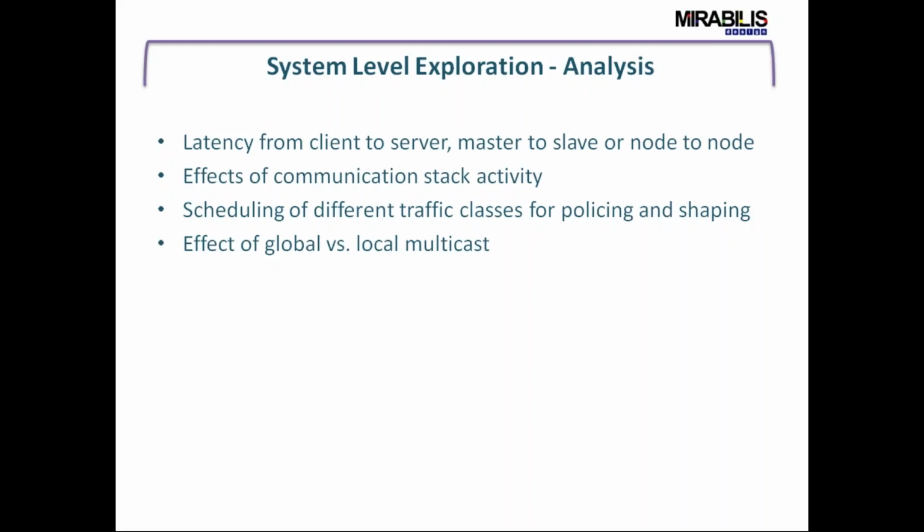Okay, for example, if you consider TTEthernet itself, it supports time triggered, best effort and rate constraint traffic. So what happens if a particular node generates these three different types of traffic, and whether the node on the other side of the network can receive the transactions in best effort or rate constraint, or what latency you could achieve with a particular traffic class.